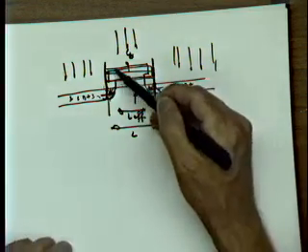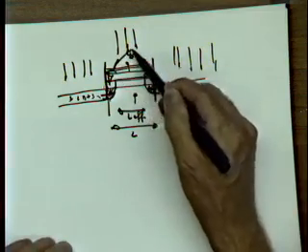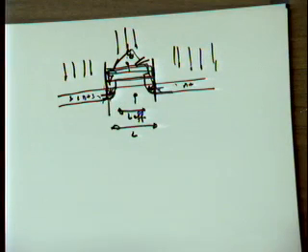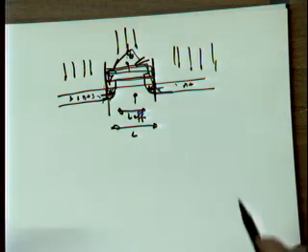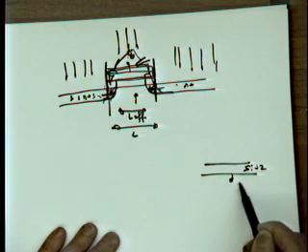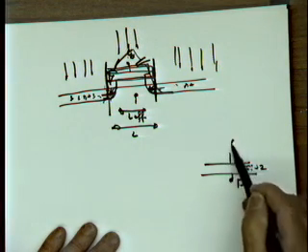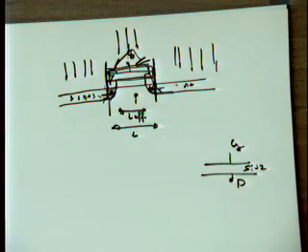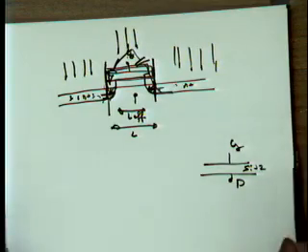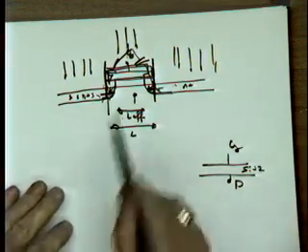Okay? And at the same time, we're going to have some fixed capacitance between the gate and the source and the gate and the drain, which are due to this overlap capacitance. Okay? That's fixed. That's a linear capacitance. Right? It's really silicon dioxide. On one side you have your drain, and on the other side you have your gate. It's a parallel plate capacitance as good as it gets. So I'm not going to talk about that anymore. That's always there.